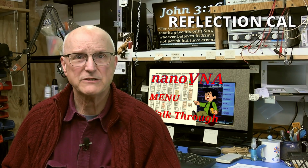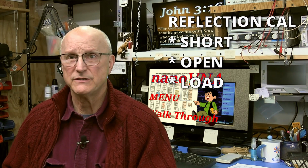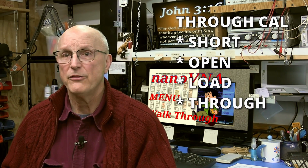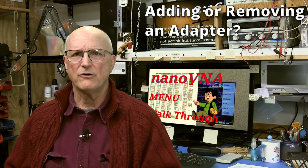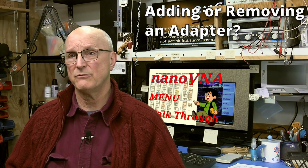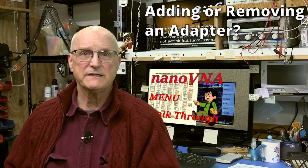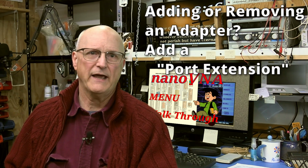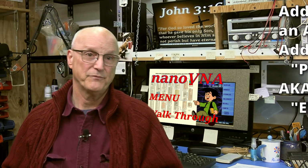For reflection measurements, you'll need a short, open, and load calibration standard. For through measurements, you will need a short, open, load, and through calibration standard. Sometimes you'll have to add or remove an adapter after calibration in order to connect to the device under test. Well, this is covered through the use of a port extension. In the nanoVNA world, this is referred to as electrical delay.